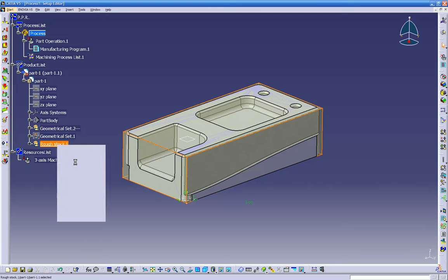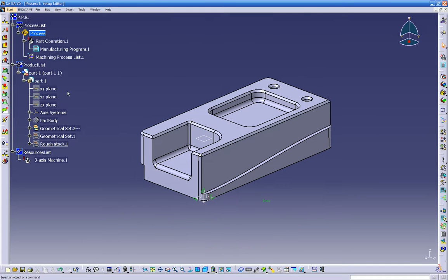Let's turn this off a little bit, and we want to try the curve following. With this option we don't have that much control. As you see, an icon, a surface, and a tool scribing basically the part. So this one is kind of like for scribing. Most of the time I don't usually use it for anything fancy, like for example this pocket in here or this contour over here. I don't use this option. I just go back to the profile contouring. So this is more like a scribing kind of operation, but I'm going to show you how it works.